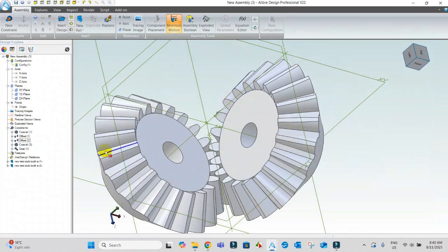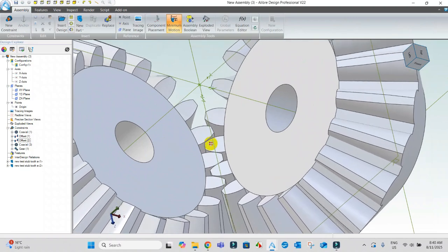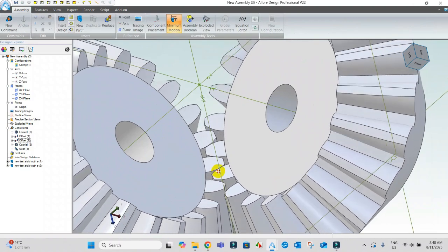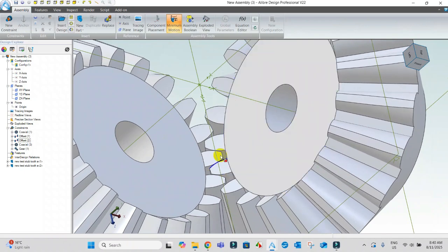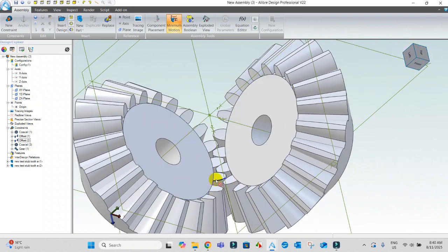Close the window. We haven't got that little sliver that I had last time, but you just see down here, the stub tooth form makes the teeth a little bit fatter at the bottom, and you see that is engaging reasonably well, but this time the clearance is on the top of the tooth, not built into the bottom of the tooth depth. We'll have a look at the other side because that's where it's really important.